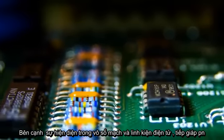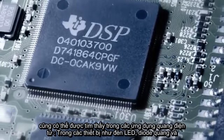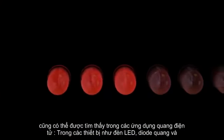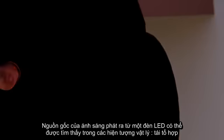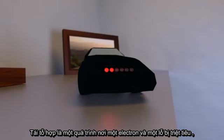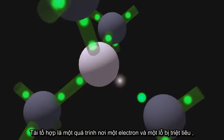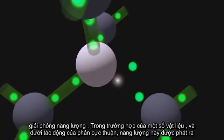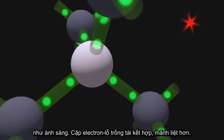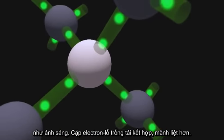Besides being present in countless circuits and electronic components, p-n junctions can also be found in optoelectronic applications, in devices such as LEDs, photodiodes, and solar cells. The origin of the light emitted from an LED can be found in the physical phenomenon of recombination. Recombination is a process where an electron and a hole are annihilated, releasing energy. In the case of certain materials, and under forward bias, this energy is emitted as light. The more electron-hole pairs recombine, the more intense this light is.